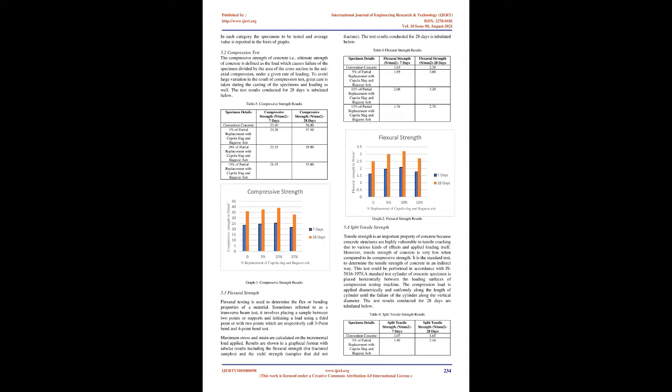It conforms to IS 383-1970 and comes under Zone 2. Coarse aggregate. The material which is retained on BIS test sieve number 4, 4.75 mm, is termed as coarse aggregate. The broken stone is generally used as a stone aggregate. Coarse aggregate used is locally available. Crushed angular aggregate of size 20 mm and 10 mm are used for this experimental work.